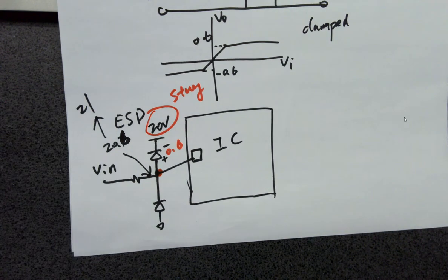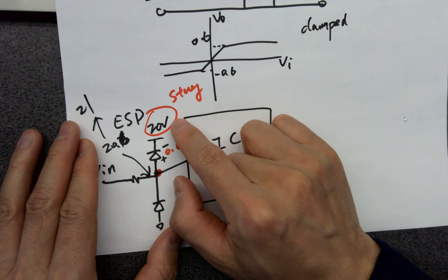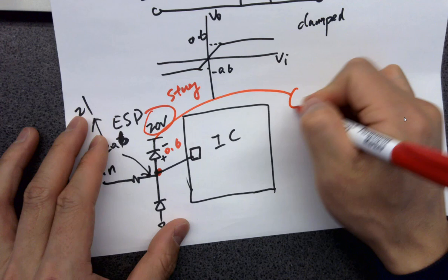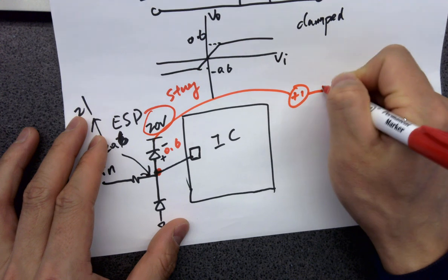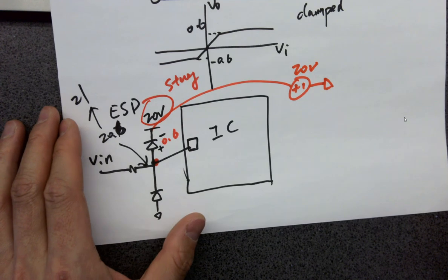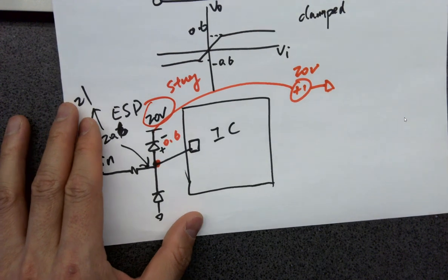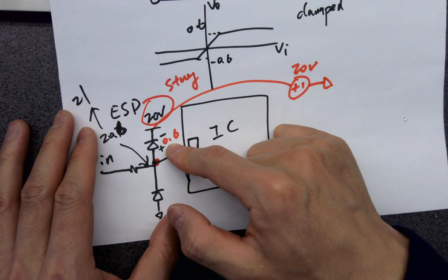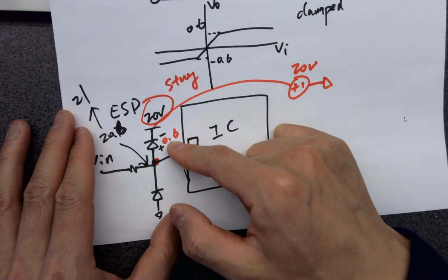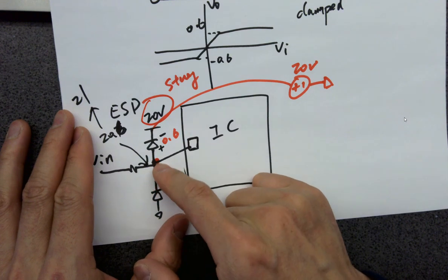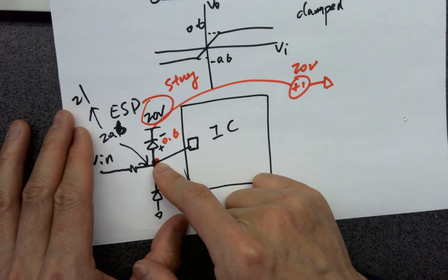KVL, okay, KVL. 20 volts here. 20 volts is what? It's like this, right? Plus minus 20 volts. That's a power supply. Plus minus 20 volts, minus plus 0.6 volts is fixed. So what's the possible voltage here? It's exactly 20.6 volts. It's not changing.